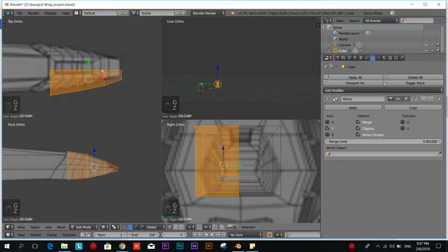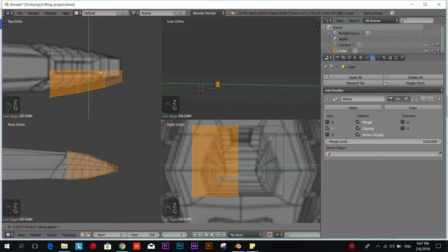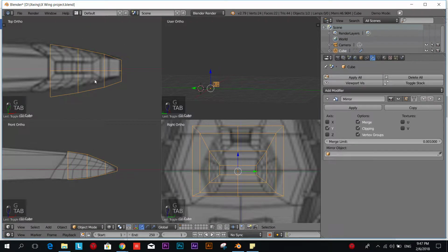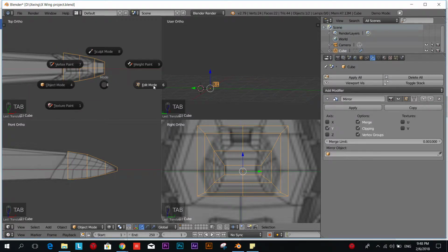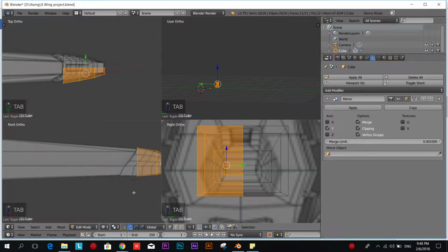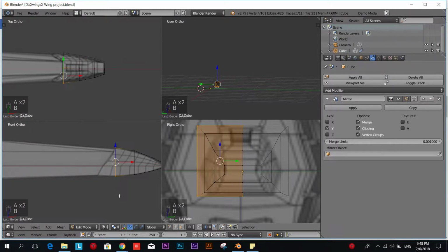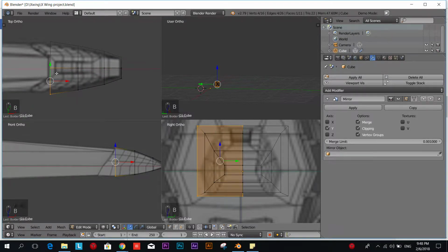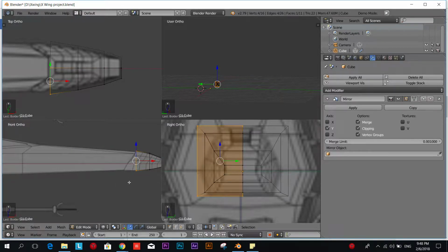We're going to press wireframe again, move it on the y, and put it back in. So now when we extrude only these vertices, the other half just goes along with the rest.